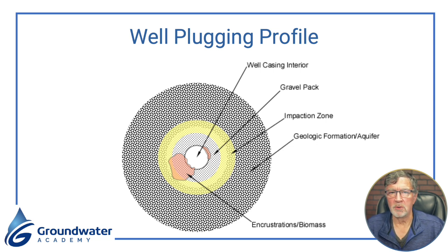The majority of what's going on is probably outside your well. So even if you run a camera down the well, you're probably not seeing everything, because it's going to be out in the gravel pack, a lot like the iceberg principle. So here we see the well in the middle there. You see the gravel pack where most of the action is happening out into the formation.